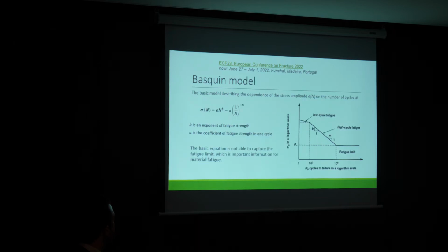Two models were applied, and one we selected for the evaluation of the results. We applied the Pascual model. You can see here that it describes very well the regime of high cycle fatigue, described by this equation, where B and A are material properties, and the fatigue limit is given at an exact point.